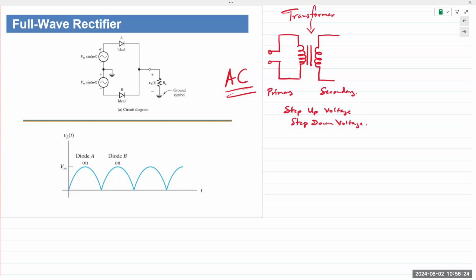In modern chargers, what it does is it converts the wall outlet, 120 volts, directly into DC. That high voltage is converted directly into DC. Then it is passed through an inverter circuit, converted back into an AC at high frequency transformer. And again, there are lots of equations that go on this, but because it's high frequency, the transformer size is now reduced. It's very, very small. It does not have to be large. So anyway, modern chargers that you use nowadays still use the exact same principle.